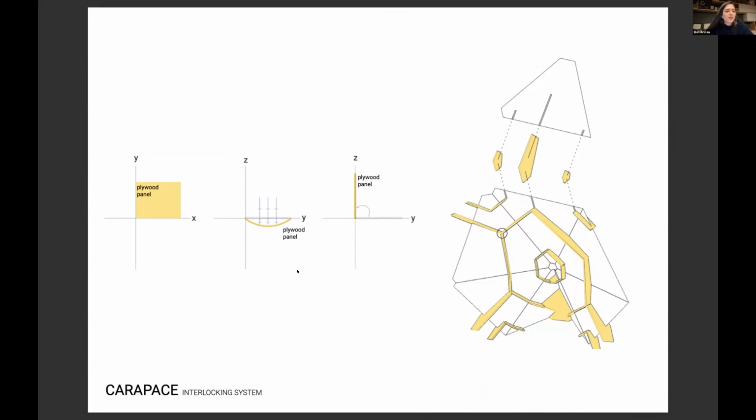So when we rotate the plywood surface by 90 degrees around the Y-axis, its section gets thicker in the Z-axis, so it becomes rigid. We use this logic, and by inserting connectors perpendicular to macroform unit surfaces, we obtain 3-dimensional strength that allowed us to lock the whole system. And the high coefficient of friction of plywood prevents slipping between the units.